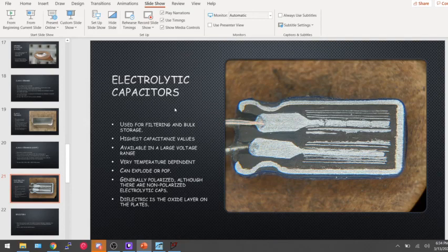And as a result, this is what it looks like on the inside. They're also kind of dangerous, not really to people, but in circuit. Their capacitance value changes a lot with temperature, and it can be very wide. And between two different kinds of capacitors, it can change very, very dramatically. And essentially, it's not so good to use in stability critical applications.